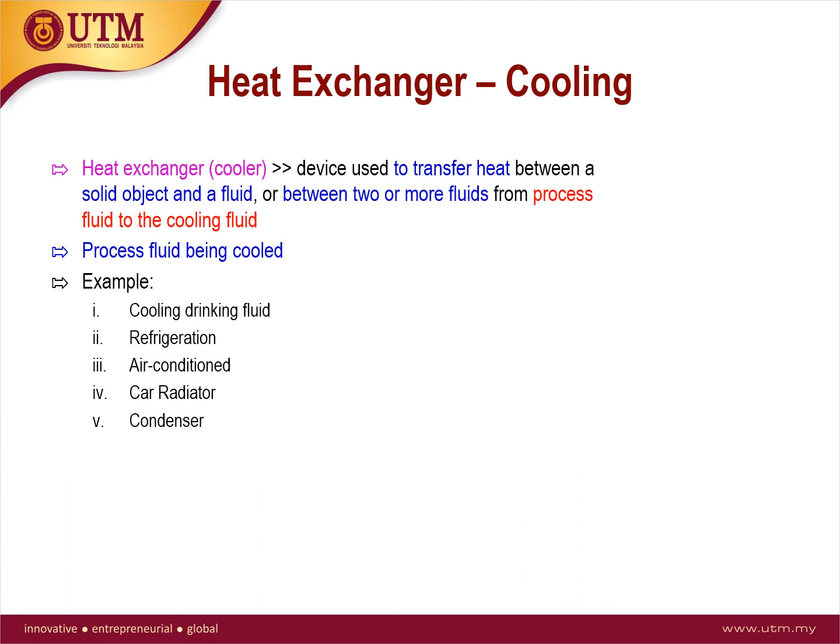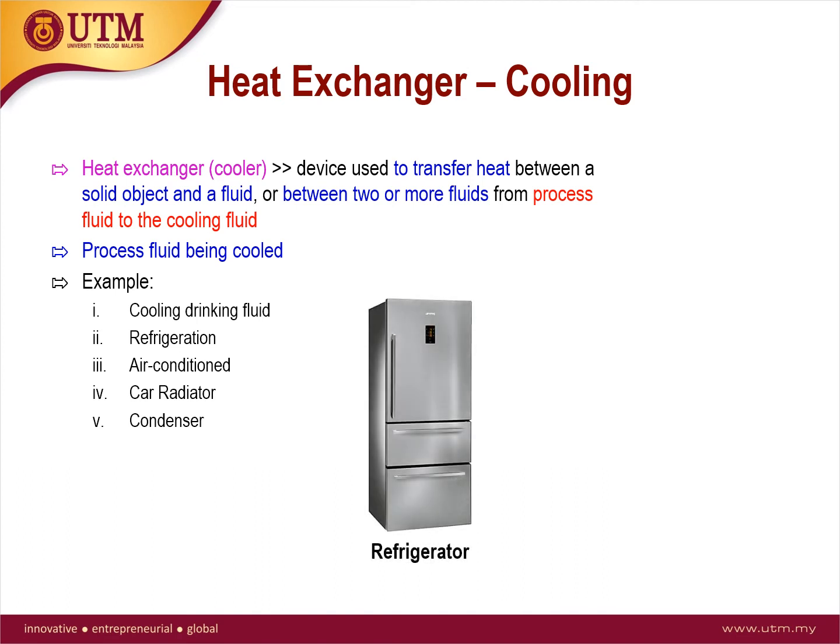On the liquid side of this heat exchanger, the common fluids are water, a water glycol solution, steam, or a refrigerant. For heating coils, hot water and steam are the most common, and this heated fluid is supplied by boilers. For cooling coils, chilled water and refrigerant are most commonly used.